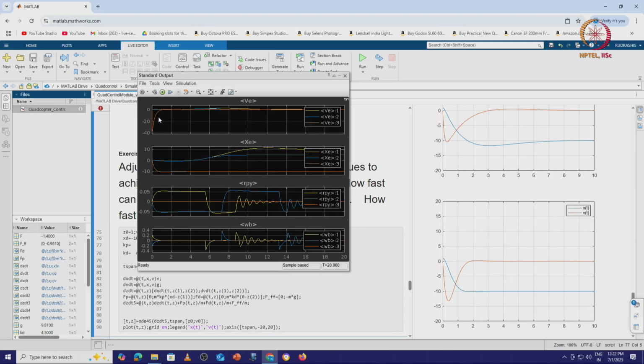Whenever we design a controller, we take an equilibrium point and linearize it. When we linearize, we approximate the system, right? That approximation of the nonlinearity does affect things sometimes. So what we do is get the PD values, substitute them in, and then simulate and verify.